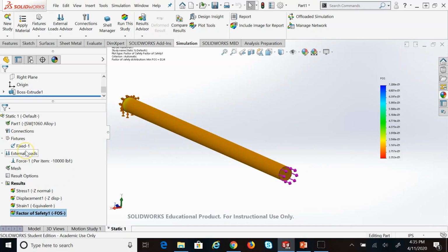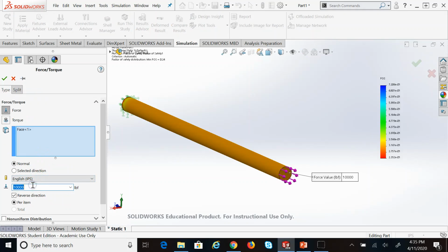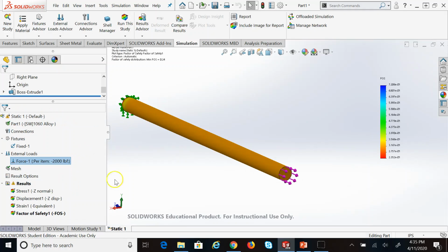So if I say, well, maybe the load was not as big as this, maybe the load was, instead of 10,000 pounds, I made some mistake, maybe it was 1,000 pounds or 2,000 pounds or something like that. Okay, it wasn't really that big. Of course, typically the load is known, so you have to modify the geometry or use a stronger material, because in a design you have 2 options, either choose the material or choose geometry or both, and recalculate everything.